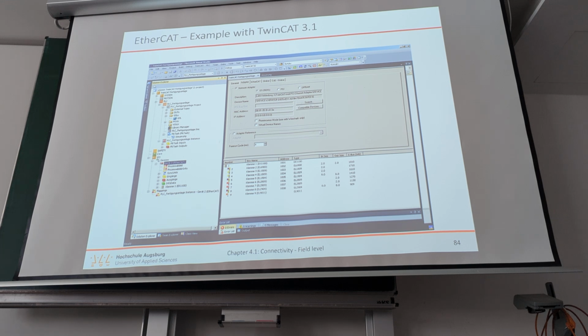They travel at 1 meter per second. No, actually, in fast forward they can travel 1 meter per second. And that would be, if you had a resolution of a micron, you would have 1 million steps per second, and you need a very fast cycle time actually to be able to control these drives in the end.